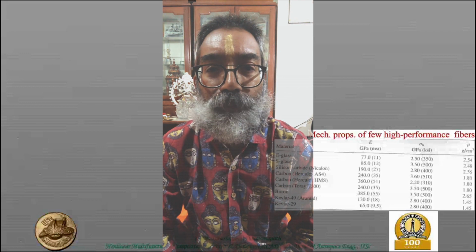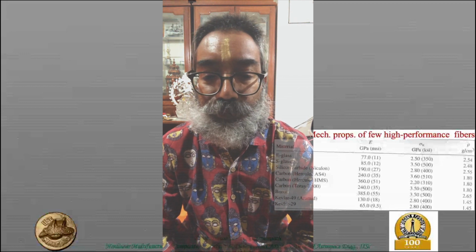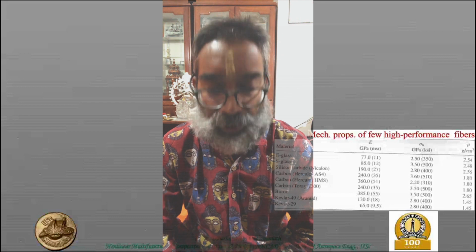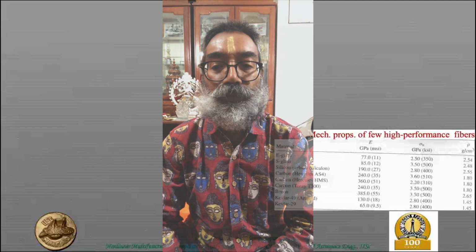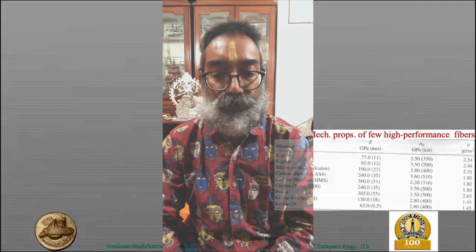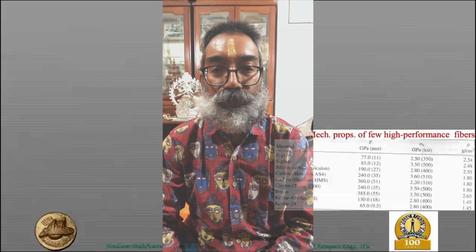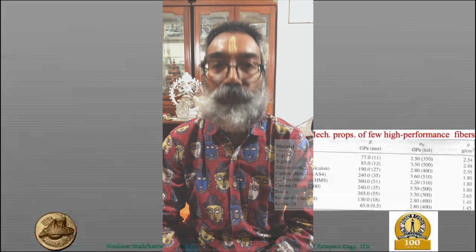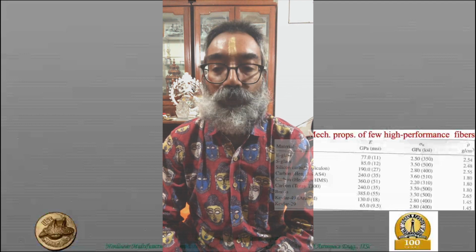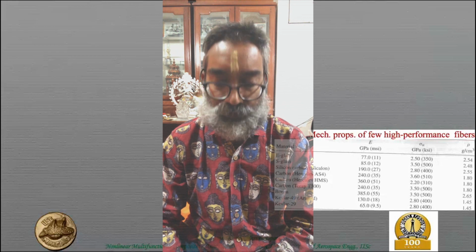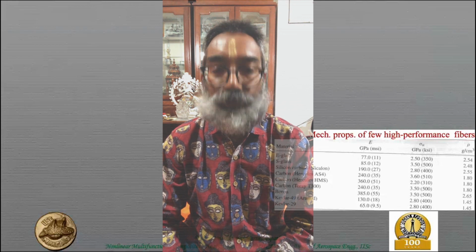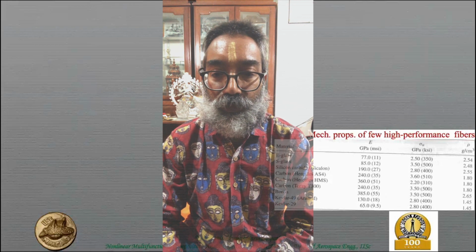Hello, sir. Good morning. This is Samanway. Yes, Samanway. You told fibers can't take compressive loads. Yeah. Okay. And sir, in your previous statement, you told we tend to make the fibers at -45 and +45, and in that case, fibers are under both tension and compression, so that they can take the transverse as well as shear loads. So if fibers can't take compressive loads, then why do we put 45 and -45?